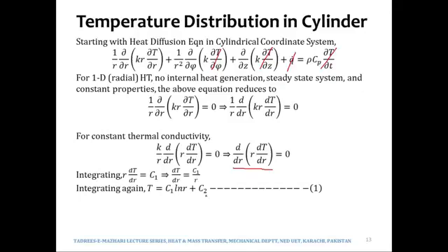Those were two very simple boundary conditions. All we said was that we knew temperatures at two locations, and the same boundary conditions will be taken over here in the case of cylinder. We will say that we know temperatures at two locations, at two radii. So we will say that we know temperature at inner radius and we know temperature at outer radius, or R1 and R2.